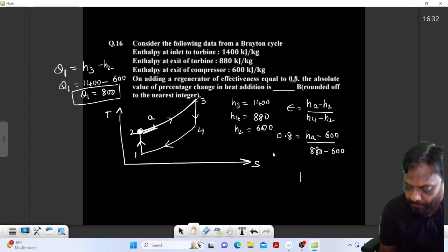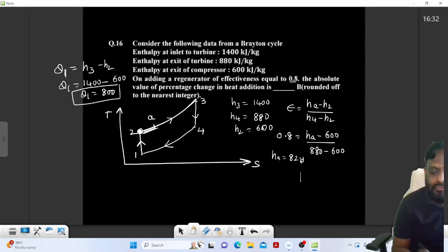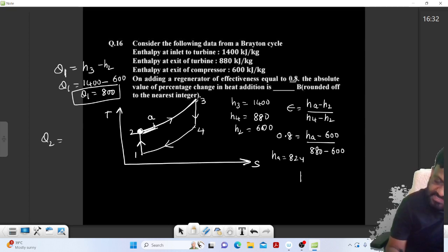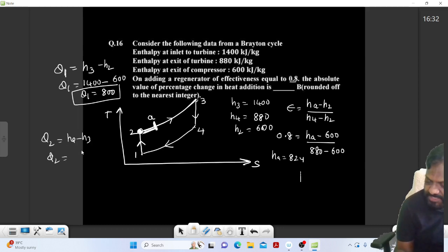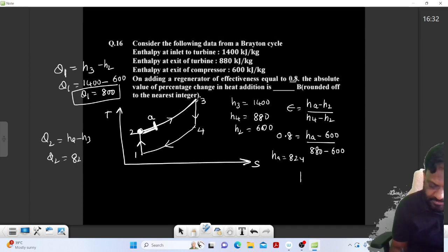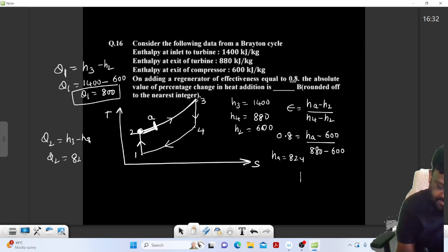It is 824. HA is 824. So what is the new heat supply? H3 minus HA. Earlier we were supplying from 2 to 3. Now you are supplying from A to 3. So Q2 will be equal to H3 minus HA. I'm sorry, it is H3 minus HA. Supplying from here to here, H3 minus HA.